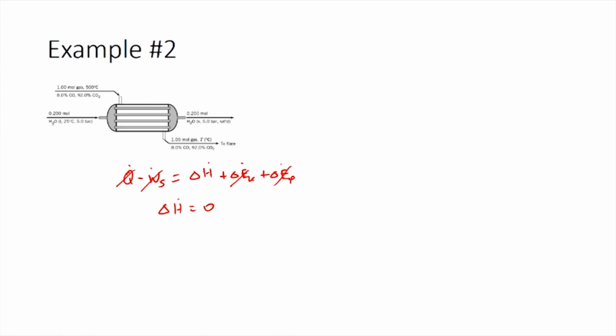So, this is useful because we actually are not trying to calculate heat transferred here, we are trying to calculate the temperature. So, for this, if we have this equation, we would actually be writing the delta H dot in terms of temperature, because we can actually get Cp value in terms of temperature and actually perform integrations, which will give us a polynomial of temperature which we can solve to get the value for temperature. So, let us try to do that.